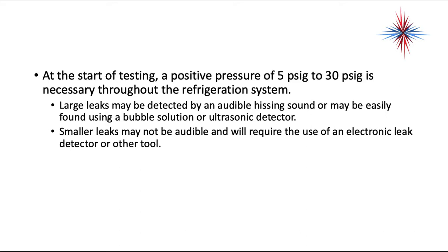Large leaks can be detected by audible hissing sounds and can be easily found using soap bubble solutions or an ultrasonic detector. Smaller leaks may not be audible and might require the use of electronic leak detectors or other tools. Okay, let's start here.